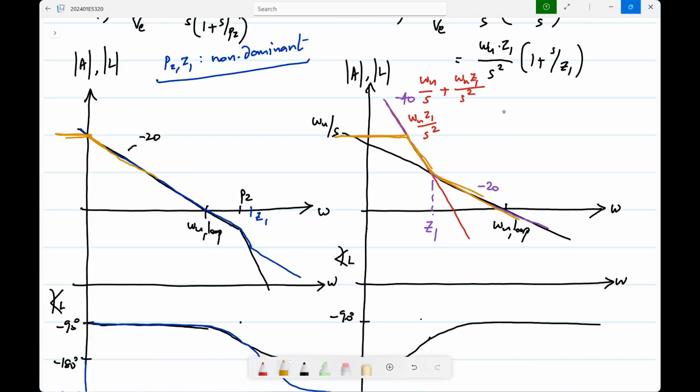No. We'll assume that after omega u loop, the negative feedback is inactive. You may have signals there, but that is not our intended frequency of operation, right? Yeah, because then it's open loop. We are making negative feedback circuits, right? So obviously, for it to operate effectively as a negative feedback system, our signals will be well below the unity loop gain frequency. So which one is better? Or you can't tell?